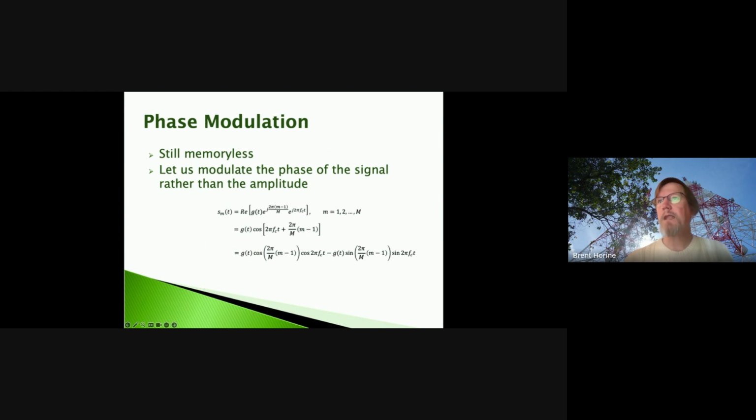So if we plug and chug here and take the real part of that, the sine term of these exponentials goes away using Euler's formula, and we're left with cosine, where this is the RF part, and this is the phase that is modulating this more constant carrier right here. Okay, and then we can use some double angle formulas.